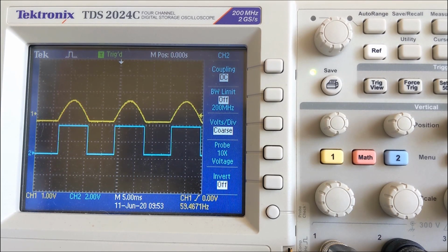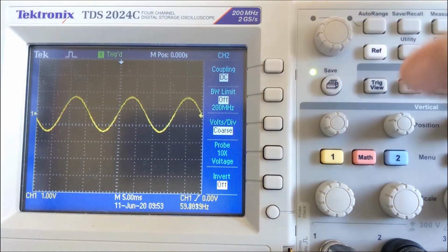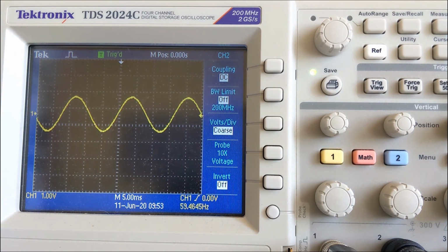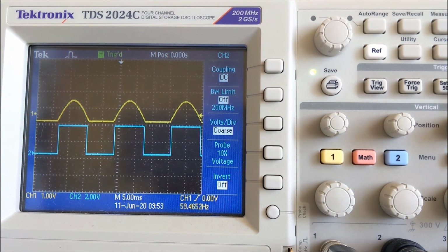You may notice that the sine wave appears to have been rectified, that is, its negative half has been removed. This is due to the ESD protection diodes on the input pin of the AVR-DA. If I disconnect the DAC output from the ZCD input, we can now see the full sine wave generated. Reconnecting the DAC output to the ZCD input via the current limiting resistor, we can see as the sine wave crosses the zero crossing point of about 0.8 volts that the ZCD toggles, creating a square wave output with a period equal to the period of the input sine wave.